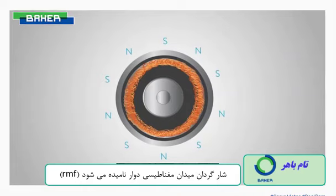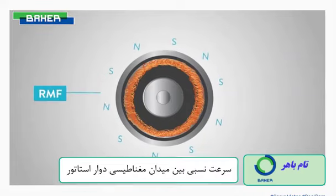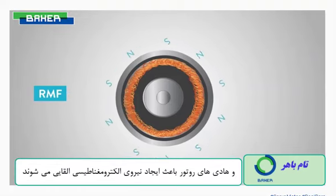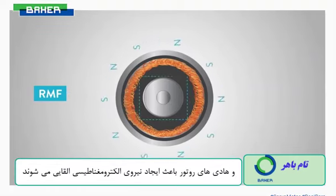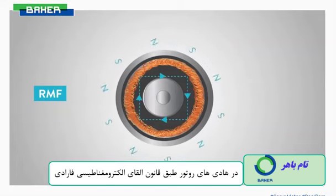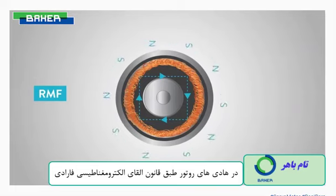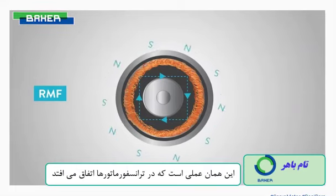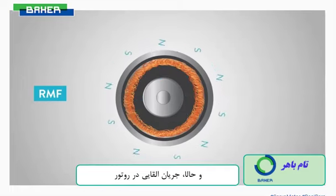The revolving flux is called a rotating magnetic field, or RMF. The relative speed between stator rotating magnetic field and rotor conductors causes an induced electromagnetic force in the rotor conductors according to Faraday's law of electromagnetic induction. This is the same action that occurs in transformers.